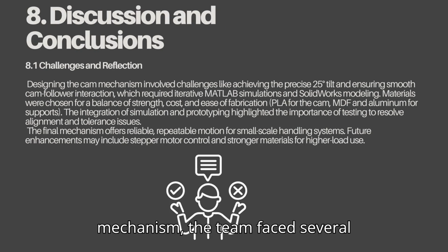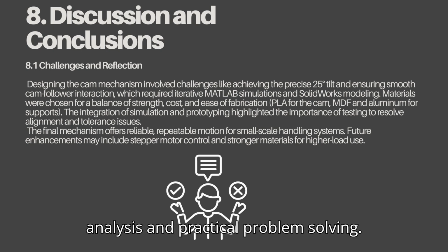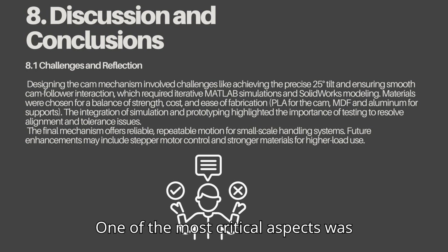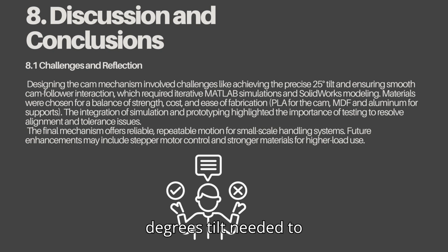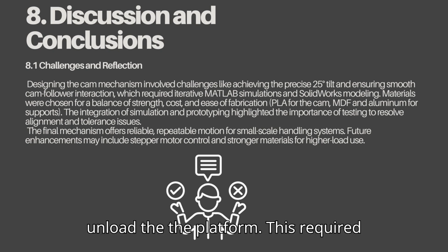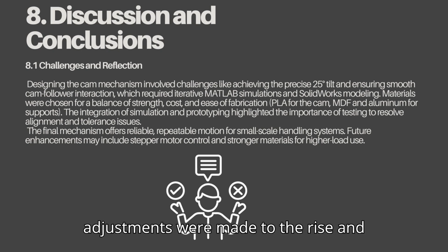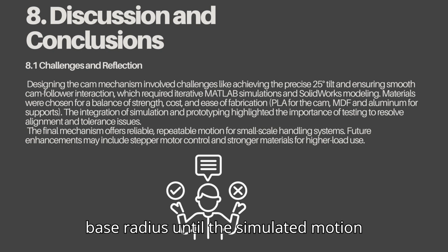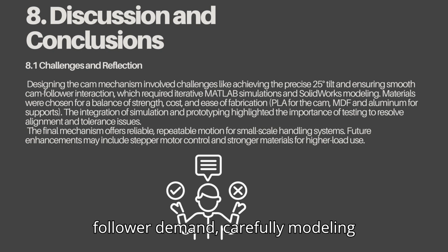Throughout the development of the cam mechanism, the team faced several challenges that required both technical analysis and practical problem solving. One of the most critical aspects was achieving a cam profile that would generate the precise 25 degree tilt needed to unload the platform. This required multiple iterations using MATLAB, where adjustments were made to the rise and base radius until the simulated motion met the design criteria. Additionally, ensuring proper interaction between the cam and the follower demanded careful modeling in SolidWorks to avoid mechanical interference and guarantee motion